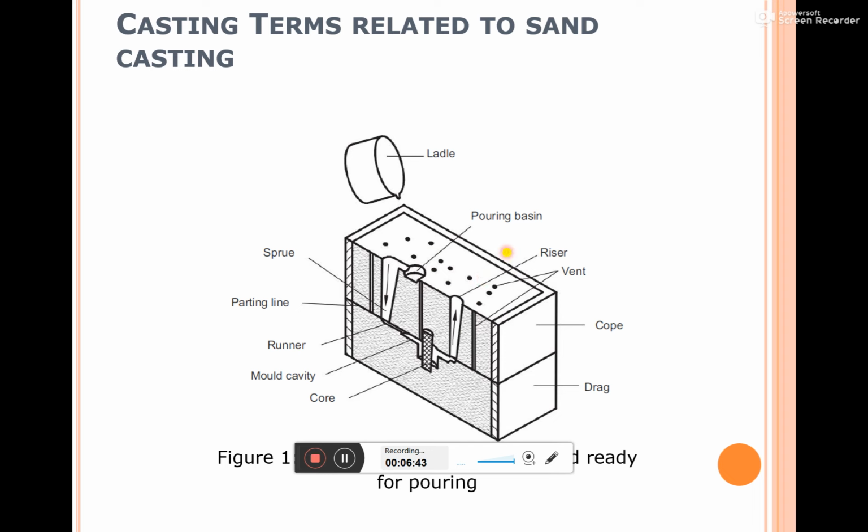Permanent molds are made up of different metals, cast iron, steel, and other steel alloy materials which have high temperature resistance property. Where such properties are required, when these types of metals are used to prepare the mold, they are called permanent molds, where you can use the mold repeatedly, a thousand or different number of times. Such types of molds are called permanent molds.